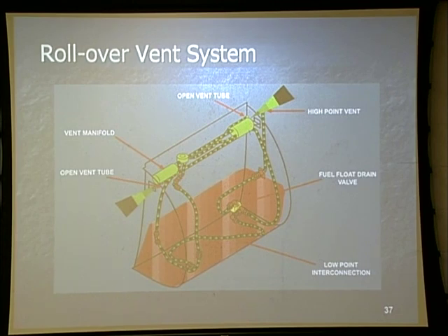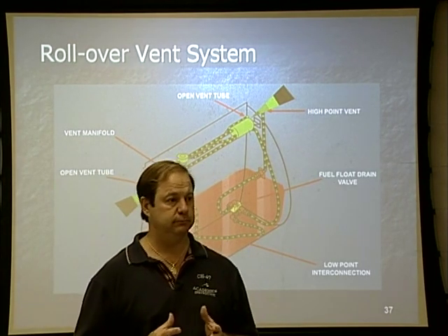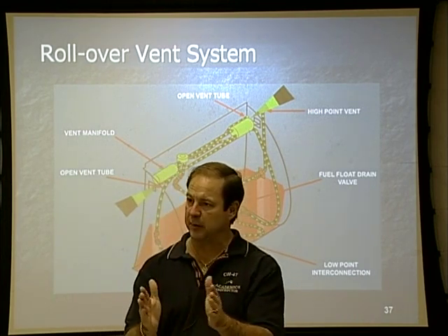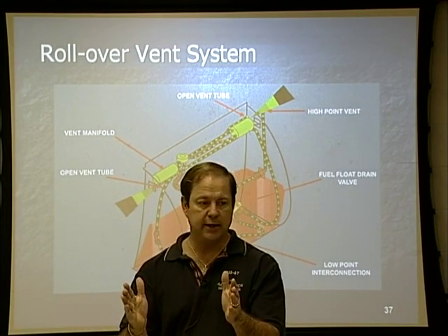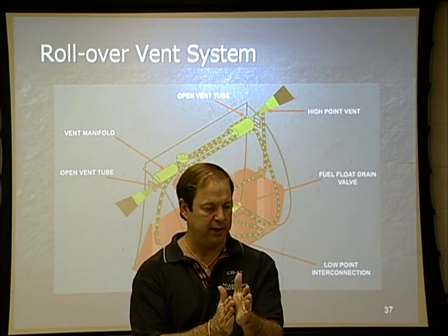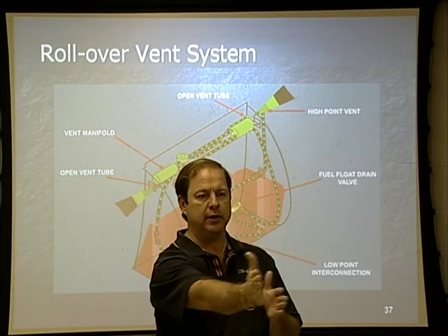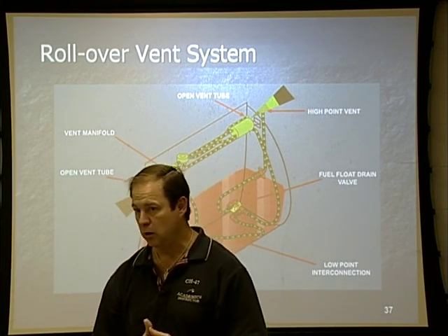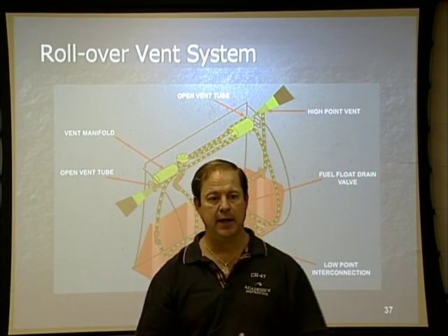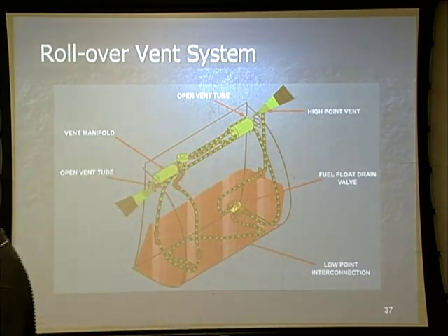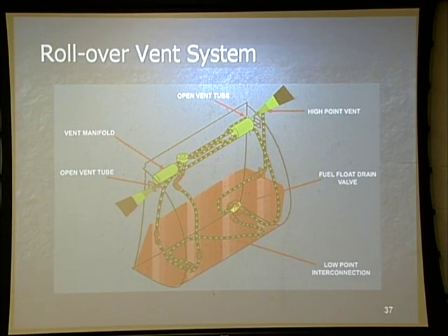Now, here's the other misconception. Fuel venting is a very bad thing for this aircraft. Why? Because as those bladders expand, and they will expand, they can actually expand to the point where on the main tanks, there's 3 major formers that run behind there. They will bend those major formers, which means we need to be able to identify it and handle it really quick. But the problem is that people waste valuable time because they don't understand the process of fuel venting.